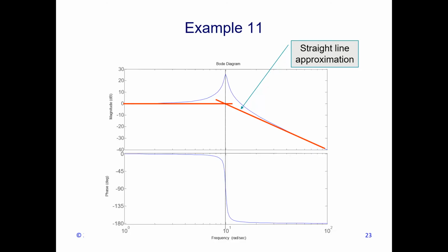Finally, what we can also notice is that the damping factor determines the stability of our system. As zeta tends towards 0, we see that our system is approaching where it is not stable at all. It is somewhat unstable. And then as zeta approaches 0.707, we approach some form of stability with the system itself.